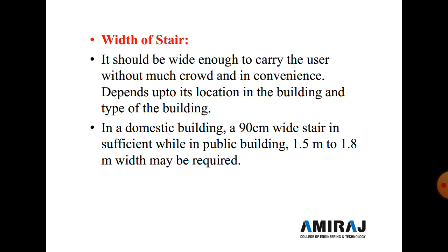So in a public building, where a number of persons get together, the width of the stair required is much more as compared to a residential building and a commercial building. In a commercial building, the width of the stair is wide enough as compared to a residential building, and in a residential building generally 1.2 meter width of the stair is provided. So it's easy for users, and there is not much crowd on a stair.